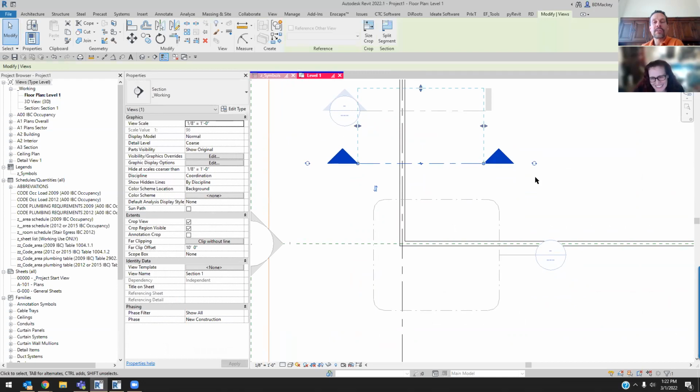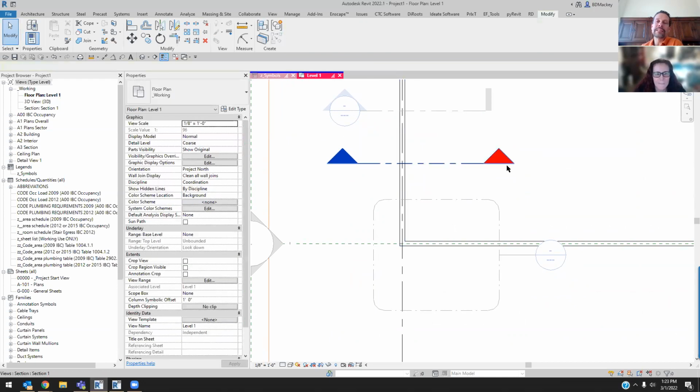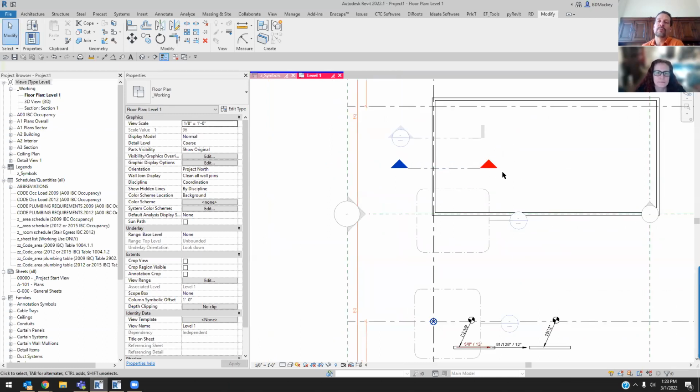These are my working sections, and my working sections by default, I just have the head be red, so I can know this is something for working. The tail is red. The head comes in blue because since it is a hyperlink in Revit, it's there. So for me, I have a whole series of working sections and working elevations and so on. So this is just, hey, all of my working stuff comes in red.